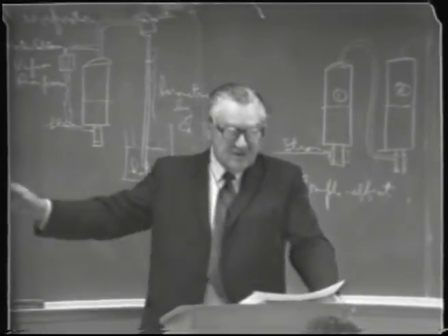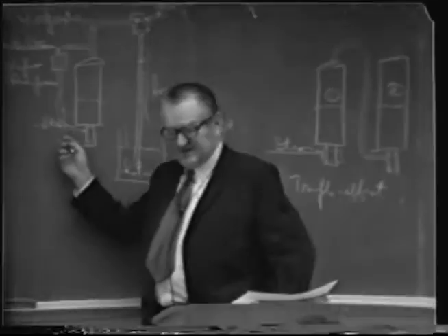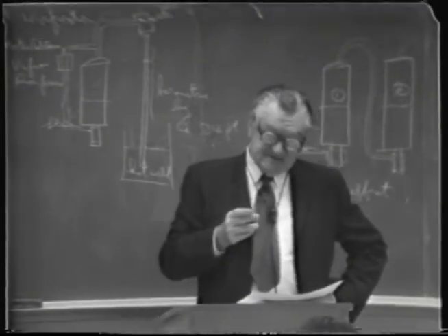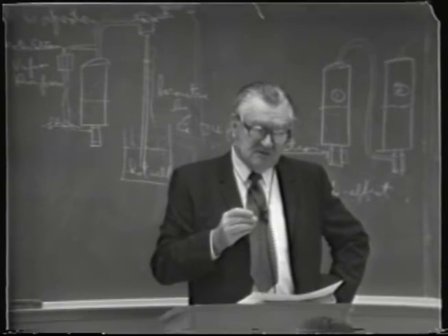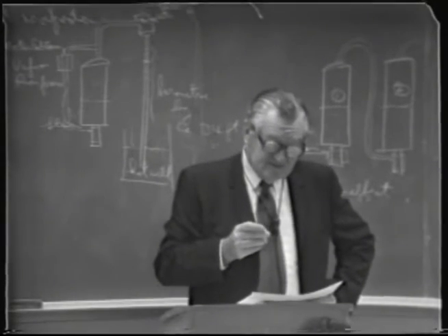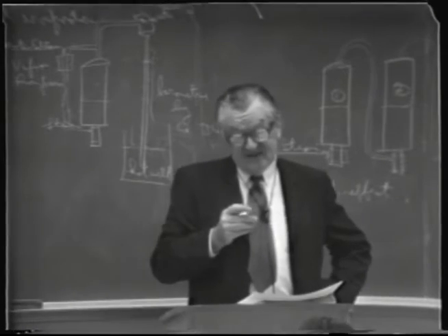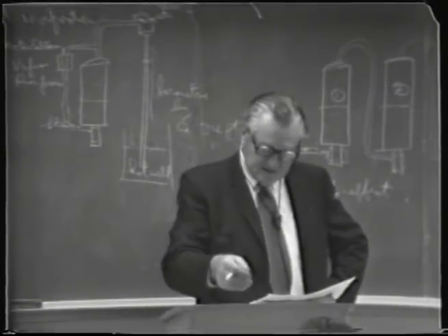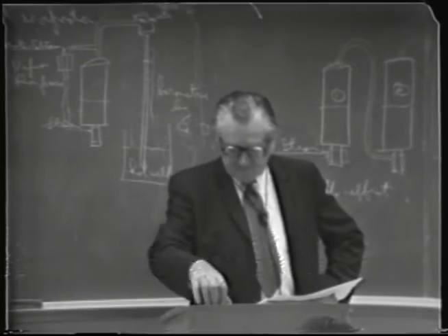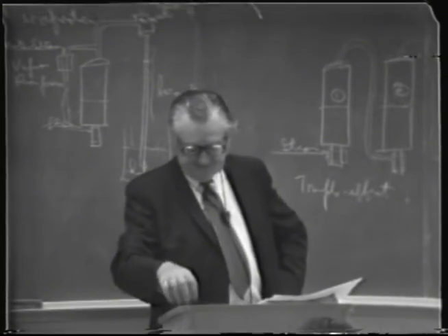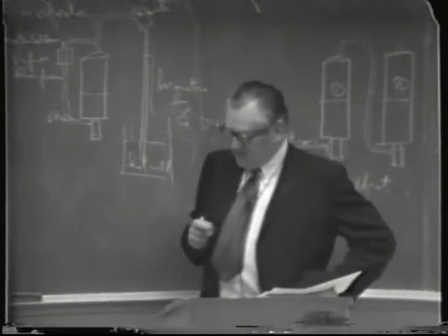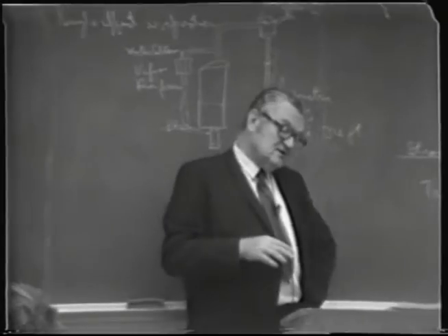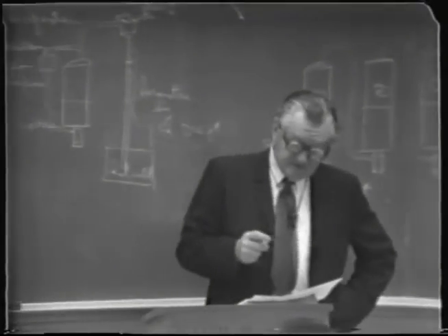So that's the reason why we're pretty much limited to single effect, or sometimes new special designs whereby they have a very short holding time. In other words, the damage done, of course, is a function of temperature and holding time. So if you can design an evaporator that can operate at a higher temperature but for a very short time, you may have no more damage than you would at a lower temperature in a more conventional evaporating system.